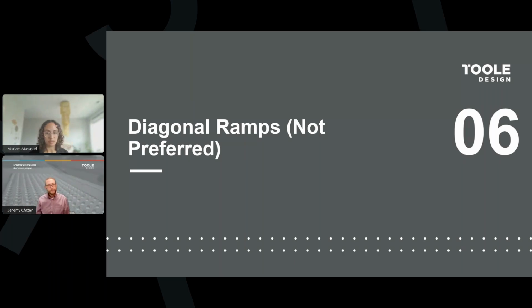Fantastic. All right. Next question is from Morgan. If you push to get the two ramps in at a corner, how much space or how high of a curb should you have between? At what point do you make it one ramp or use blended transition ramps? Yeah, at least 2 to 3 inches to ensure that that curb is going to have some detectability to a pedestrian on the back side of it, and potentially more importantly, so that there is some amount of curb reveal so that drivers aren't encroaching into the pedestrian space.